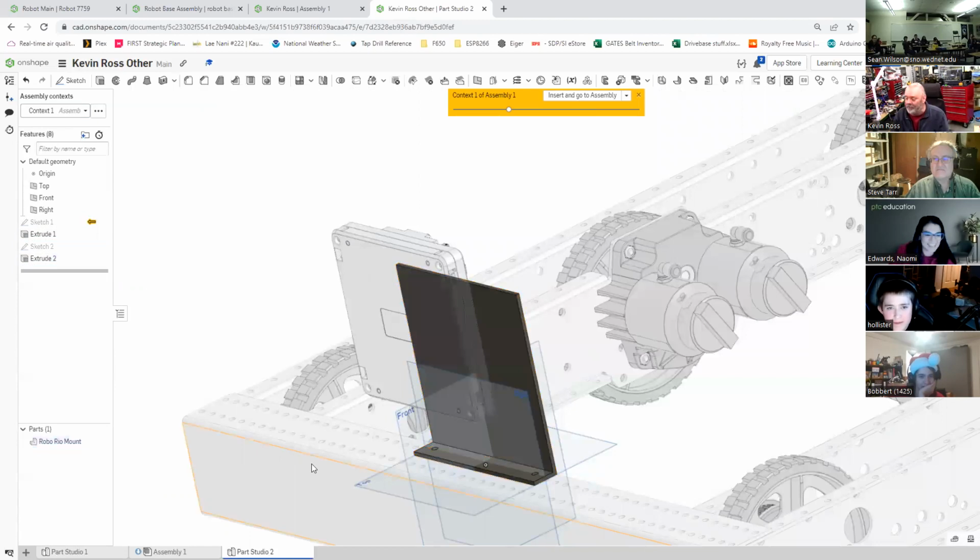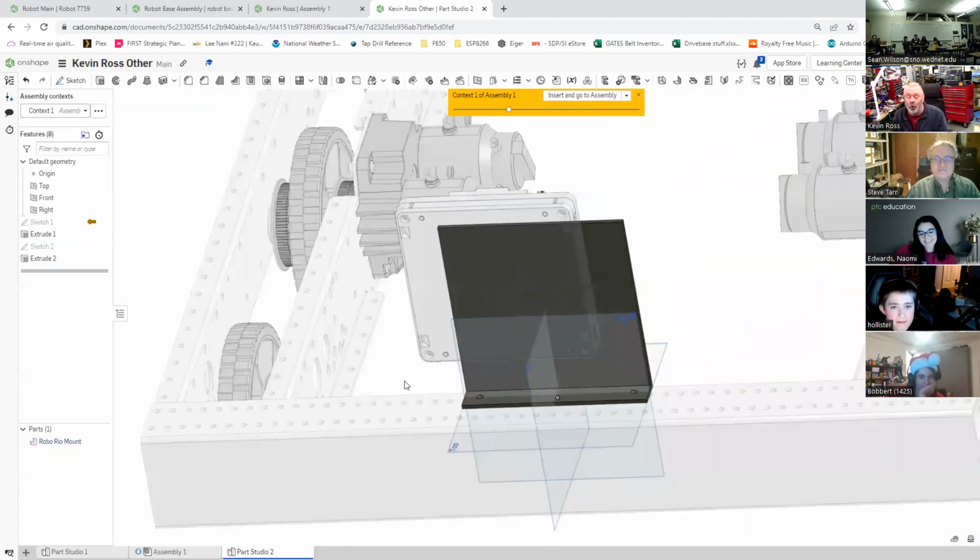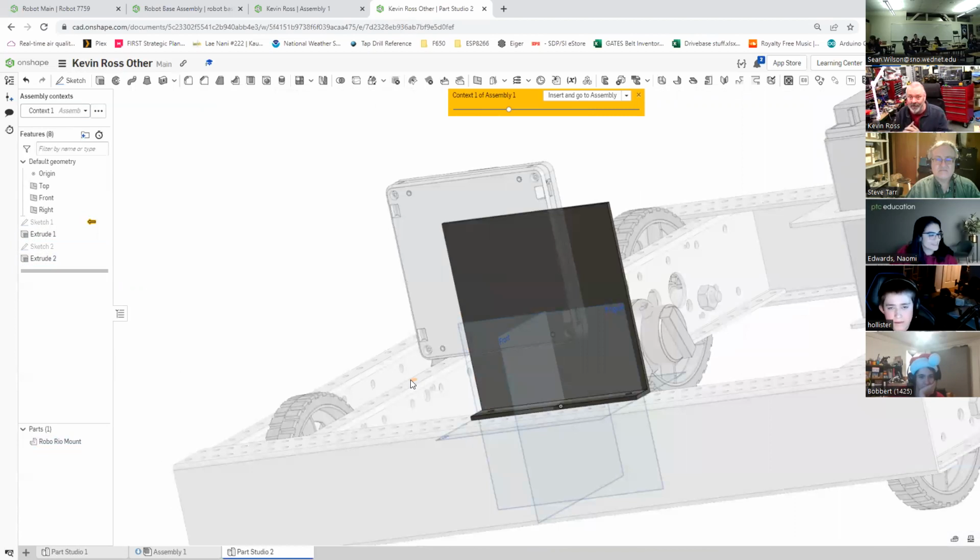Okay. So now, and this is super important, folks, when you're building parts like this. If you want your CAD to be accurate and you want to be able to find the center of gravity of your robot, yes, you want to do that, especially if you're hanging. If you do this as you're building parts, or even as you're importing parts, assign the material and give it a proper appearance. Every time you make a part, do these 3 steps. Rename it to something legitimate, assign the material, and edit its appearance so that it looks like it's supposed to, especially if you're making libraries.